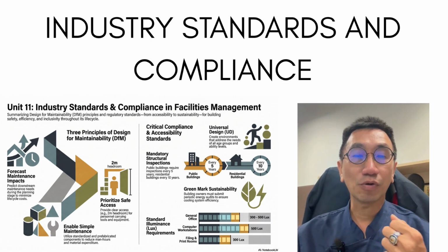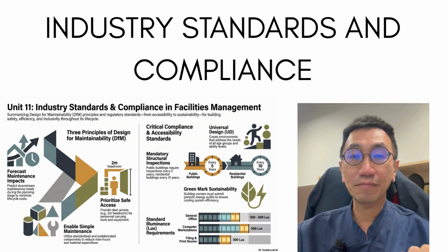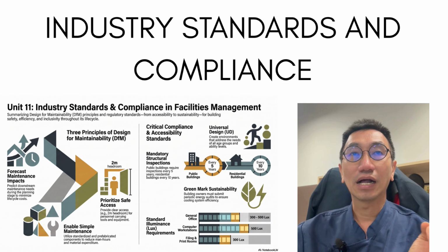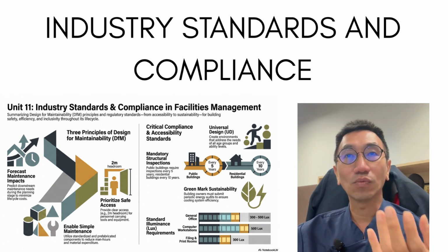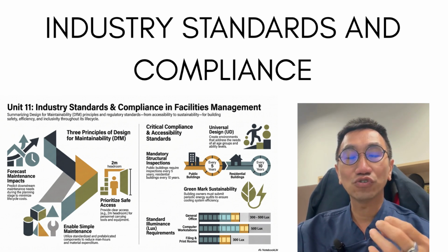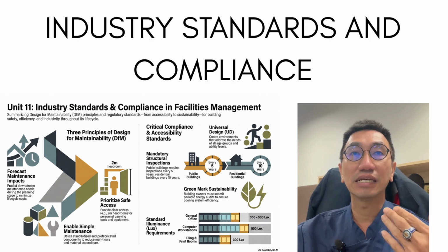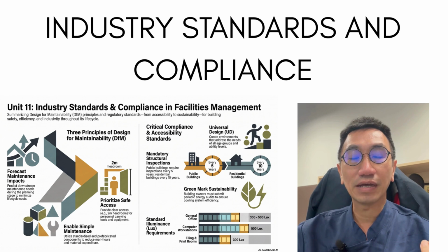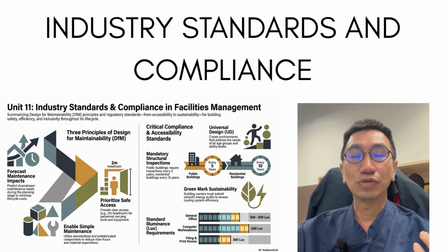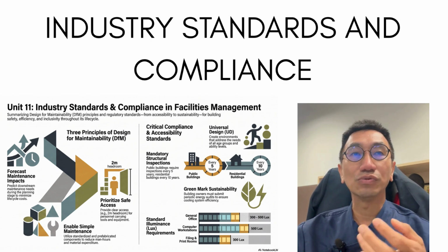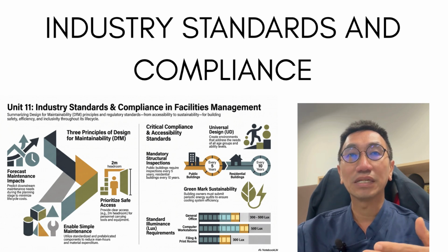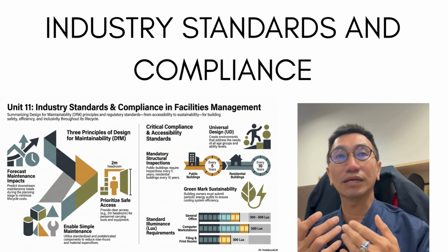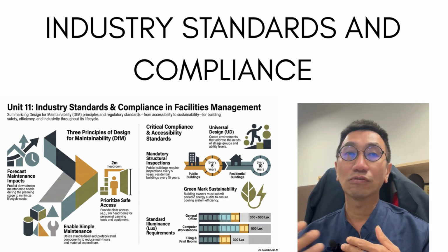So with that, point number one is DFM, which is design for maintainability, which is why buildings are designed from day one so that future maintenance is made as easy as possible. The benefit of integrated DFM at the planning stage is that it will drastically reduce downstream maintenance cost and minimize manpower.